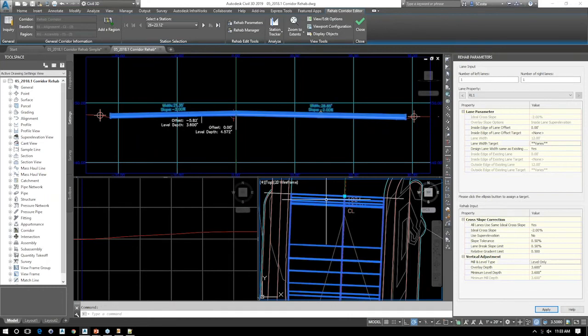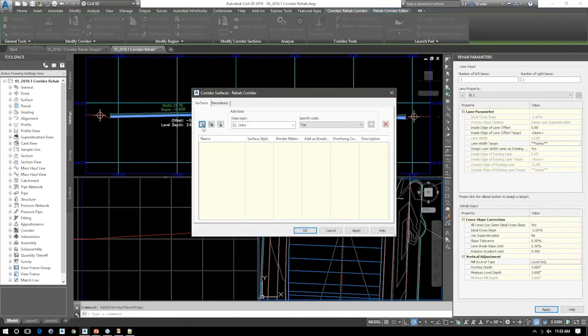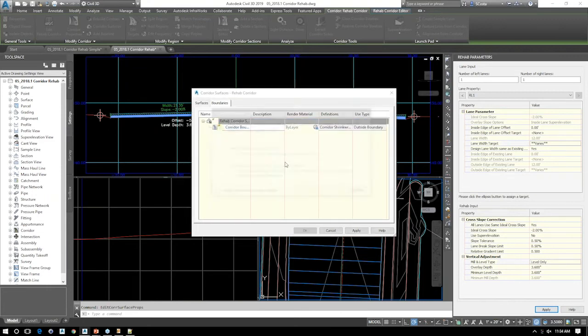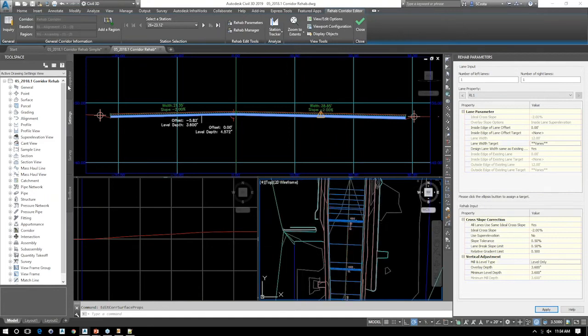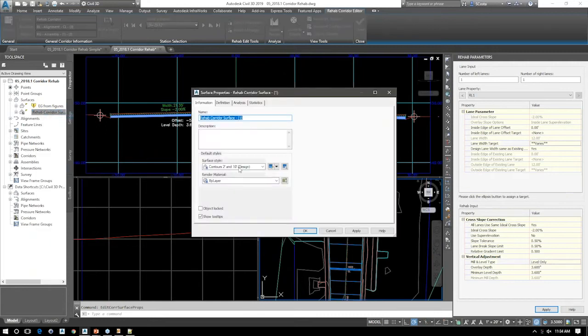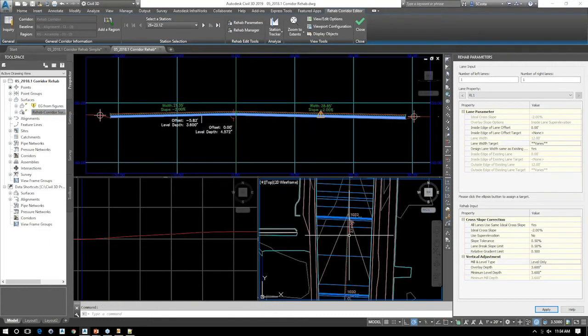As you know, you're going to want to create a corridor surface, and I'm just going to simply add the top of that corridor to this, include top lengths for overhang, and just throw a quick boundary around it as out-of-door lengths, right? So then I get my corridor surface, which I think I need to update the style for so that you can see it at 1 foot and 5 foot design, right? And so you can see what changes are occurring.